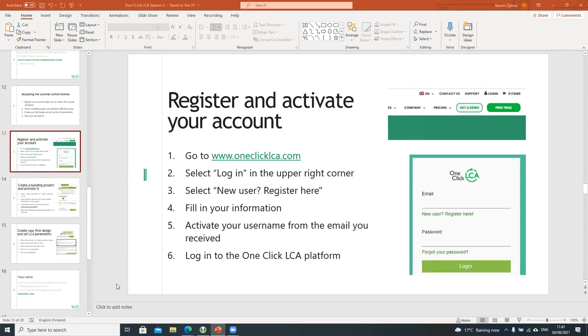An anonymous attendee asks, which life cycle assessment parameters need to be selected? Well, you can select whatever you want, but if you're doing a normal assessment, you should at least do the transportation, because otherwise you don't have data for that. We should, of course, have our service life values, so we know when our materials are replaced, and probably you want to have the end of life also. So those I would do as defaults. They also say that they're mandatory normally if you do it.